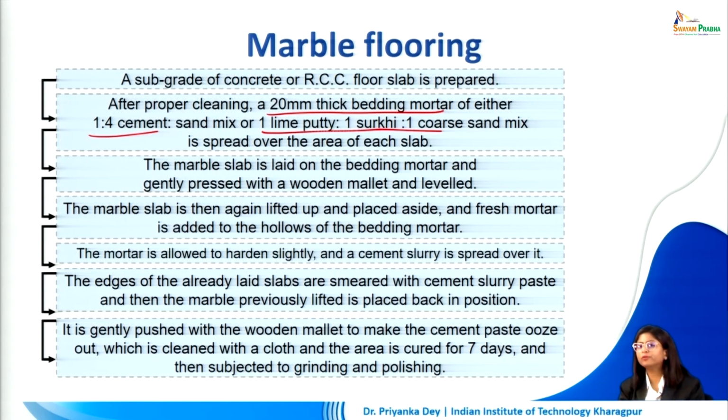That is cleaned off with a cloth and the area is cured for 7 days and then subjected to grinding and polishing. Now, depending upon the usage of the room, amount of water that this surface might be exposed to, we can determine how much polishing or grinding we want to do on the overall surface. That will determine the smoothness of the marble flooring.